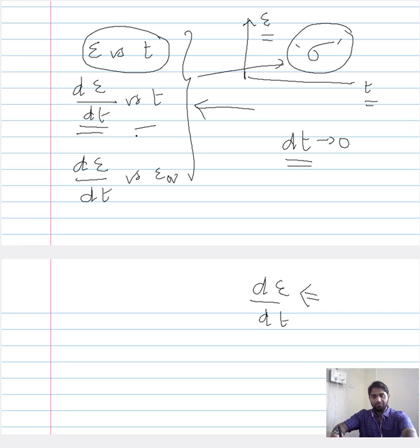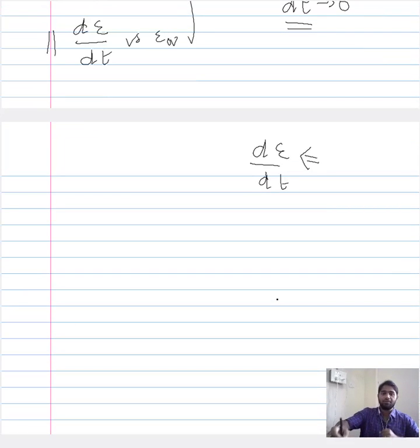So this information we can get from these two plots, that with time during the creep behavior the strain rate would vary. Correspondingly, in order to ensure that the strain rate is constant, the mechanical condition that you impose should also vary. So that is one way of representing the stress strain curve.